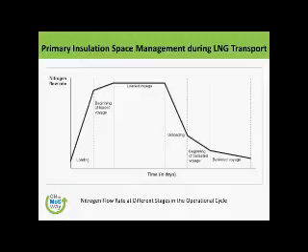Loaded voyage, more or less steady, nothing changes. Unloading, goes down. Beginning of ballast voyage goes further down. Ballast voyage further, and then at the same time it starts again. So nitrogen management in the interbarrier spaces or annular spaces is also very important.